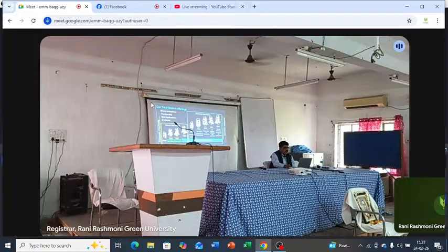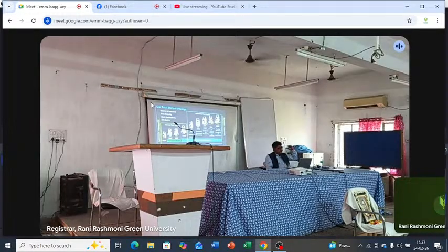Now if we go towards the automated total stations, PS13 is the starting model, then PS16. These are very popular models in India. Then comes PM16. M stands for monitoring, which means it works unmanned.